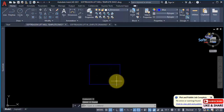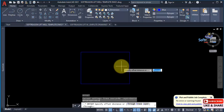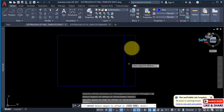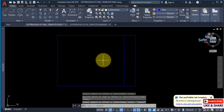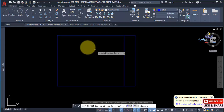All right, so in a back sheet or a title block, we do have where we have the information of the project. So we will be offsetting from this point inward. We will have 60 right there, like this. We will have something like this. Okay, in this provision is where we are going to be having all the necessary informations. All right, so also we will have a border line. Okay, for the border line we will use 5 millimeter. All right, 5 millimeter, just like this.